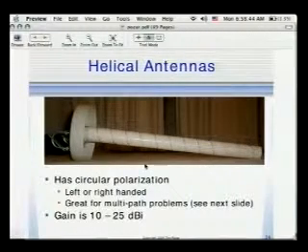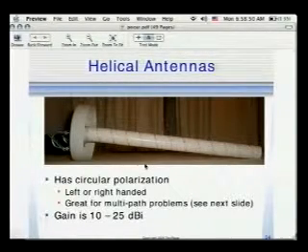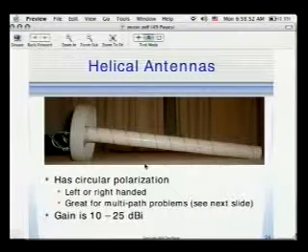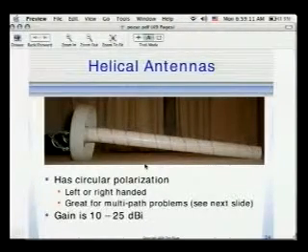The nice thing about helical antennas that are circularly polarized is that you don't have to care whether it's a horizontal body of water or a vertical building. The left-handed or right-handed polarization of the circular antenna will reverse no matter what. If it's a horizontal or vertical reflection, it'll be the opposite and therefore attenuated on the other end. You'll find a lot of ENG trucks use helical antennas because they can't predict what sort of multipath they're going to run into.